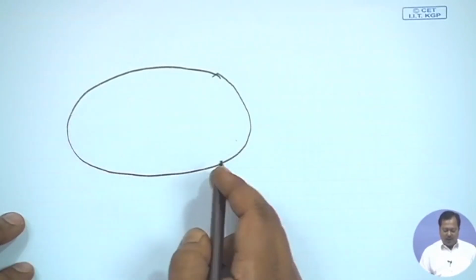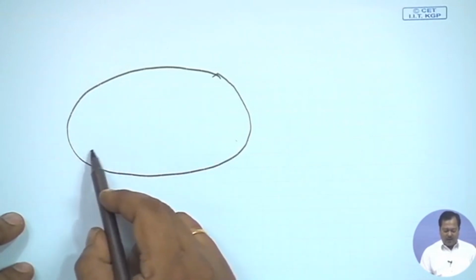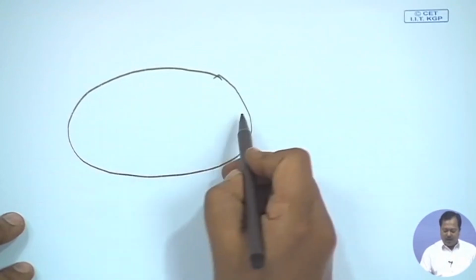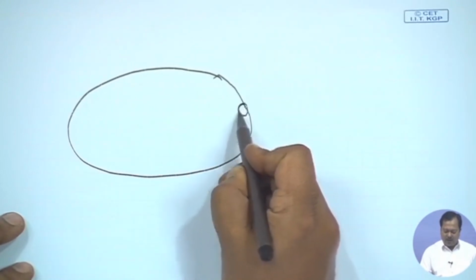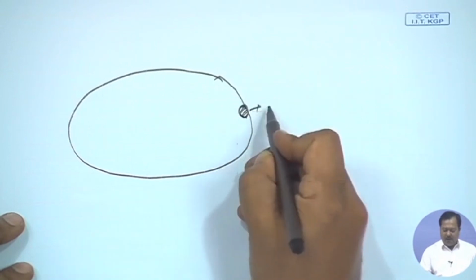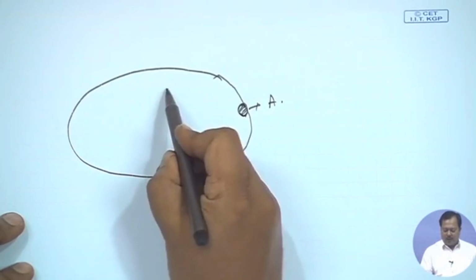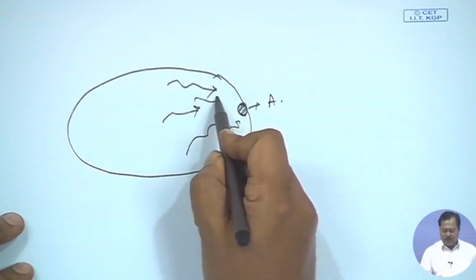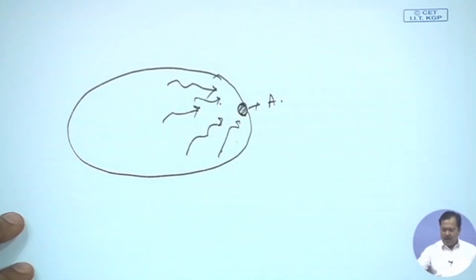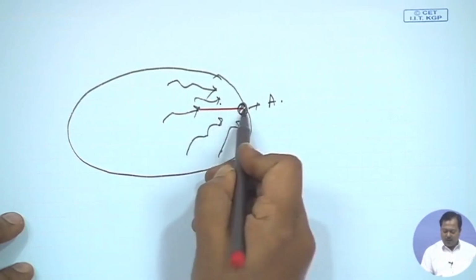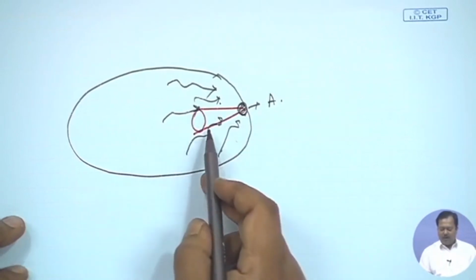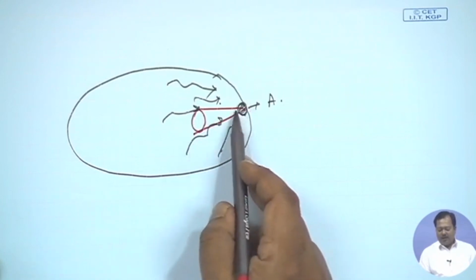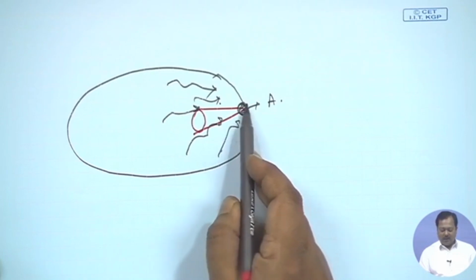It's made of a black body, and inside it is radiating due to its temperature. Let's say radiation is falling on a surface here of area, let's say A, and we want to calculate it. Now, radiation is coming from all different angles over this, and we are defining one unit solid angle, and calculating the radiation coming through this unit solid angle, and then we integrate it over the incident area A.